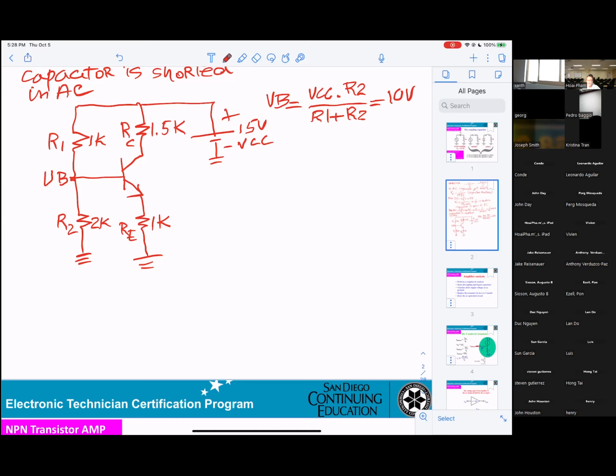When you apply for a technician interview, they are not asking you to do the calculation. However, they want to know how we get the VB. Then the answer will be VCC times R2 divided by R1 plus R2.